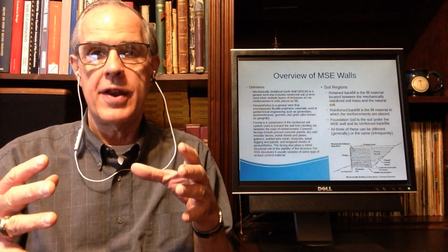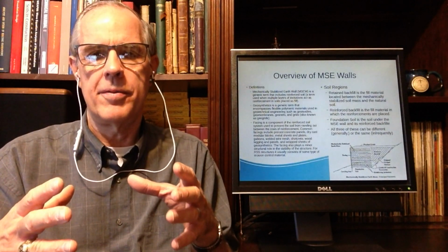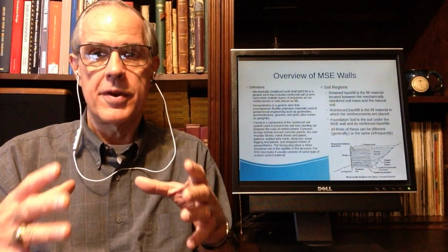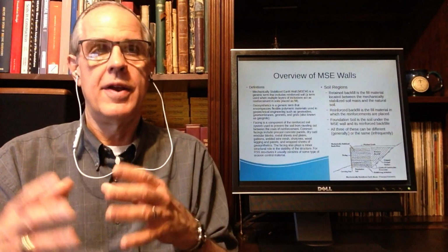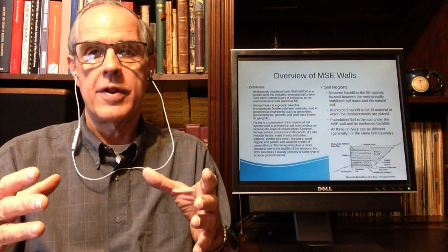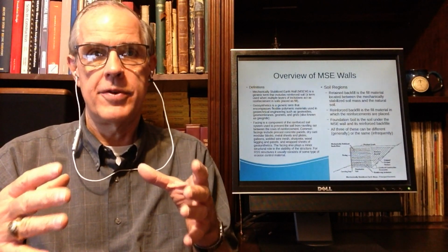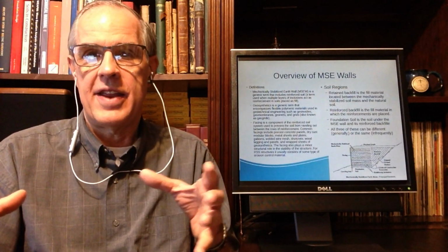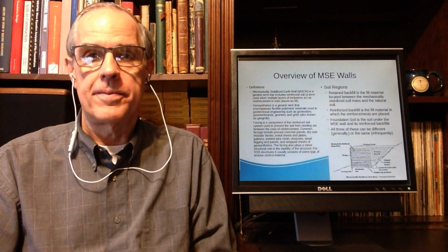Well, if you've got a granular medium, and you do that, then the granular medium is going to compact just by volume. And we talked about volume considerations last time I mentioned them, and therefore that's one way of compacting soil, by actually driving enough material in the ground so that the rest of it has to push against itself together, and that's how they compacted it.